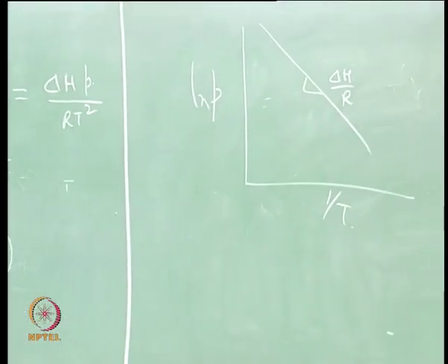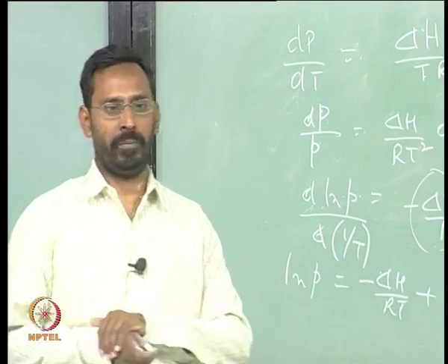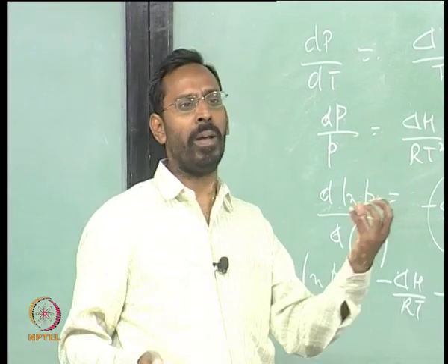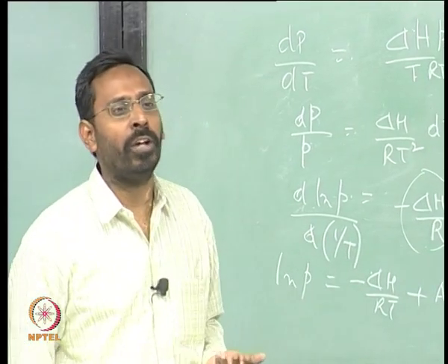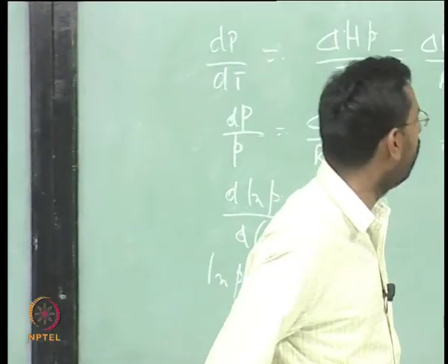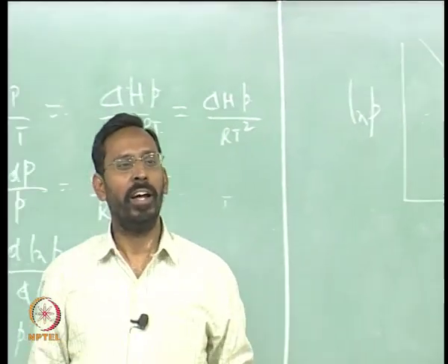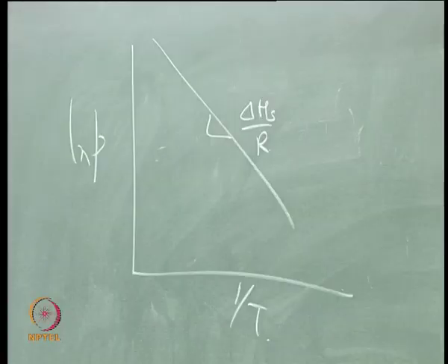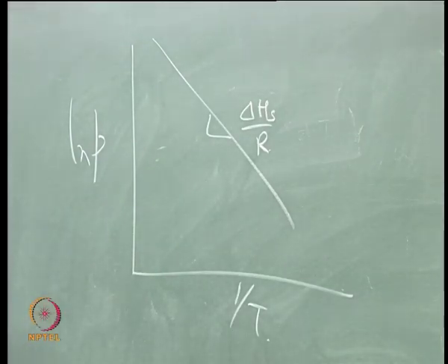This is expected because if the delta H associated with sublimation is very large, then at any given temperature you need more energy for the sublimation. So, the amount of gas molecules generated from a solid are always going to be lower if the delta H is large. So, particularly when we are looking at metals with a higher boiling point, a higher boiling point basically means its delta H of sublimation is very large. That is when you will have a very high boiling point. So, whenever the sublimation delta H is very large, you would say that this material is more difficult to sublimate.